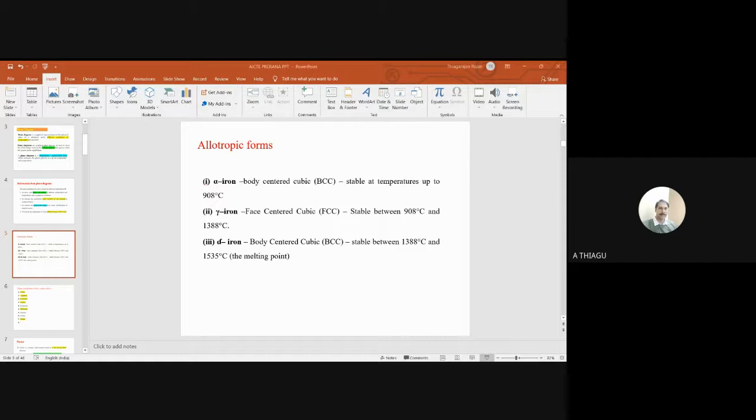Due to the absence of graphite, unlike the previous case where we saw flakes, needle-like appearance, here we don't have any needle-like appearance. The absence of graphite gives a light, white appearance. The unique properties of white cast iron are extreme hardness and abrasion resistance, but the drawback is its very brittle nature.